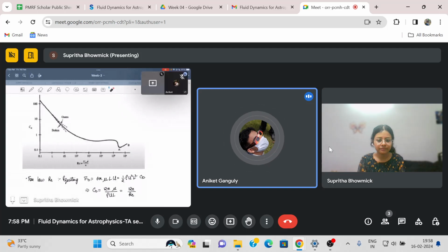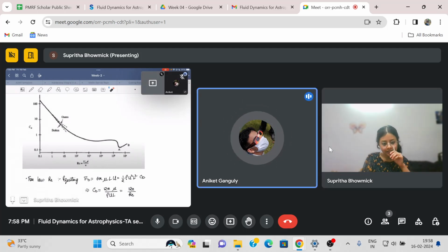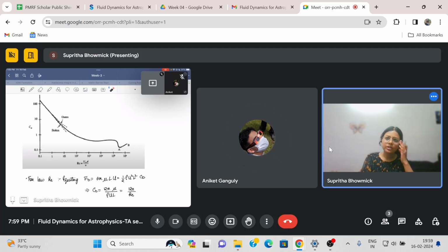Is it the same phenomenon which happens in submarine blades? What happens in submarine blades? I read about some phenomenon in which, due to high velocities, there is a formation of bubbles, small liquid-free zones, which can damage the submarine blades. Is it a similar kind of phenomenon, or something different? Vortices are not fluid-free zones. They are regions of extremely high curl U.